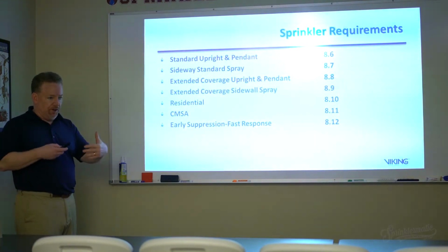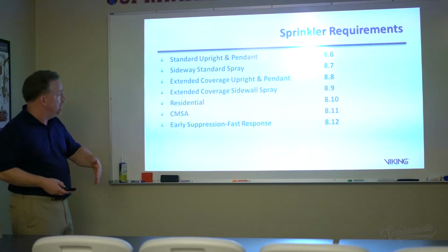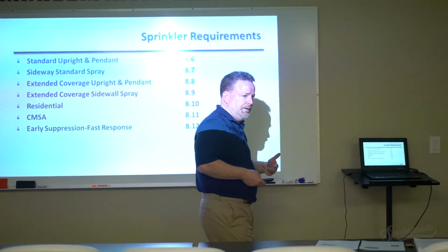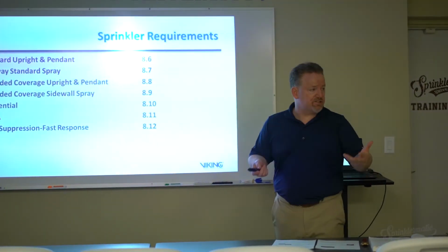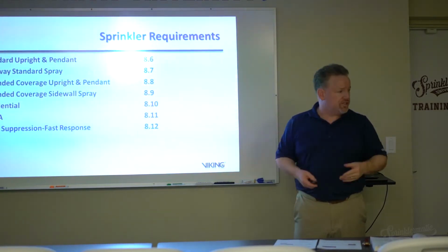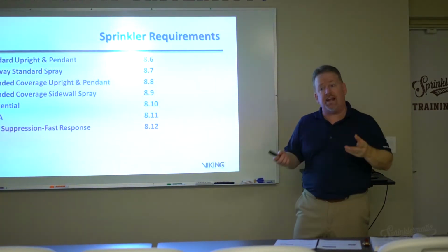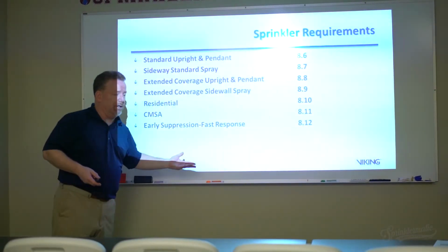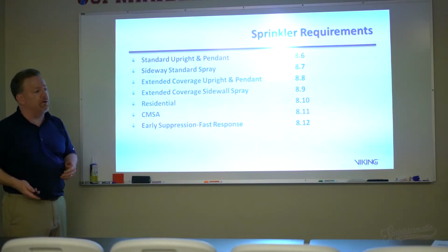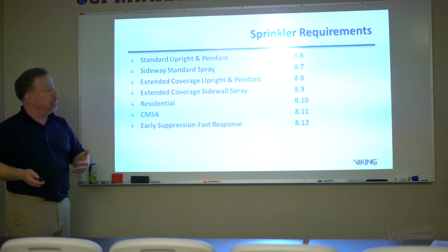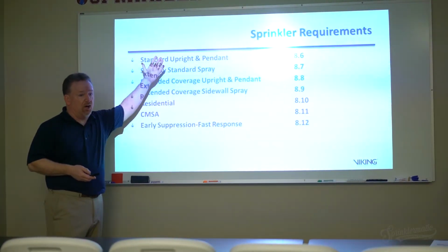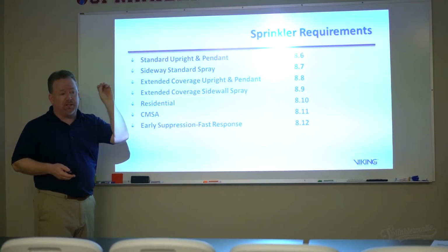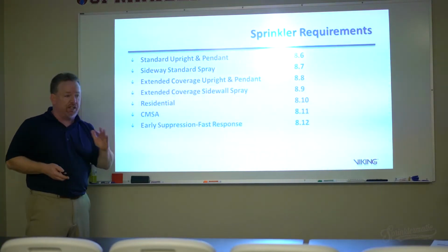I will tell you that there are certain types of sprinklers out right now that aren't covered in here. One of them that we're going to talk about on Thursday deals with interstitial spaces, the protection of interstitial space, and the challenges that come along with that, and also attic sprinklers. They're not in this list anywhere. They have special installation rules that come along with their listing, with the way they were tested. So when you're protecting an attic, you're not going to NFPA 13 per se. You're using 13 as the base rules, but then you're following the specific listing rules for those sprinklers in those areas.